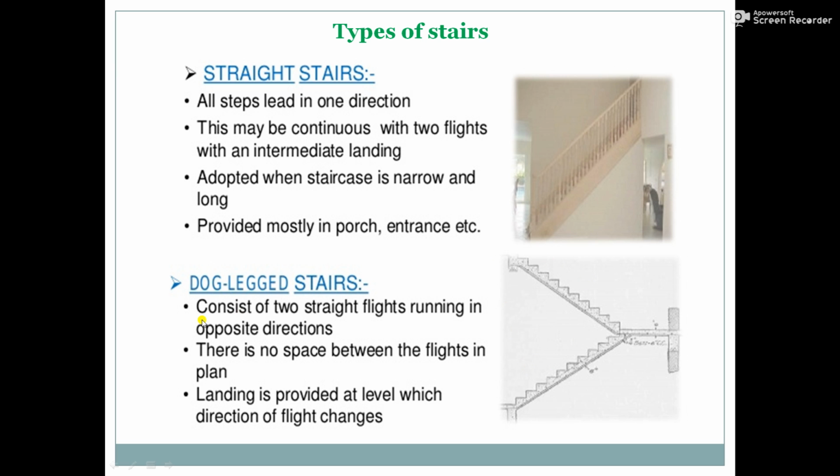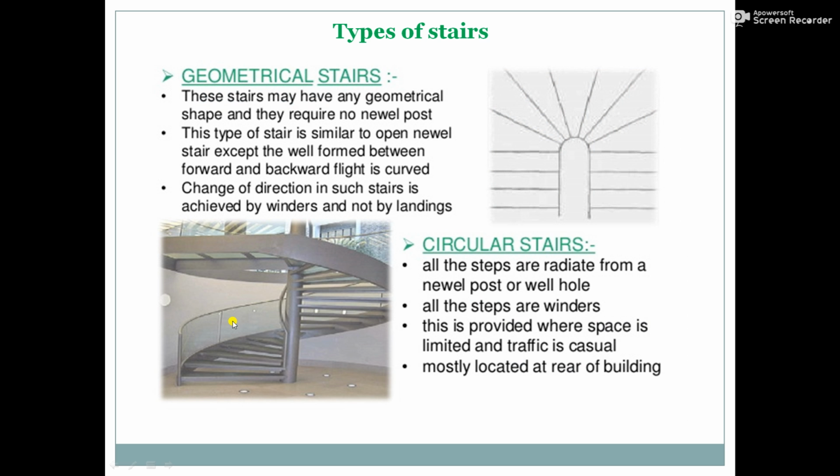So these types of staircase are known as a dog-legged staircase. Then the next, that is the geometrical stairs. These stairs may have any geometrical shape and they require no newel post. These types of stairs are similar to open newel stairs except the well formed between forward and backward flight is curved.